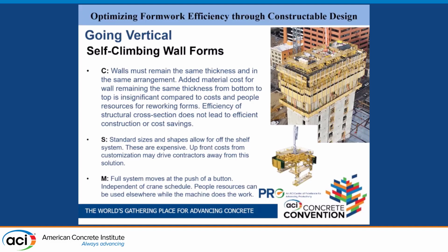There was a presentation, I think, yesterday where they were talking about how they did column design. They took their design program output, threw in the information, and it put information directly into a column schedule, and away they ran. If they're changing those column sizes every single floor, level to level, that's going to add cost.